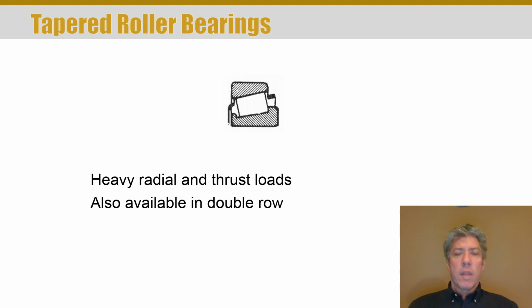Not only can the bearing innards, basically whether it's a ball bearing or a cylindrical type of roller, be different, but the quality and the materials and all of that make a big difference from manufacturer to manufacturer. So if you stick with a name brand, you can pretty much switch out to anything, but you have to be very careful. And one of the temptations is to buy cheap Chinese bearings at this point in time. Chinese make some good bearings, they make some bad bearings. And so the temptation may be to just buy the lowest cost bearing, but there's no guarantee that that bearing is really any good. We'll talk more about that a little bit later.